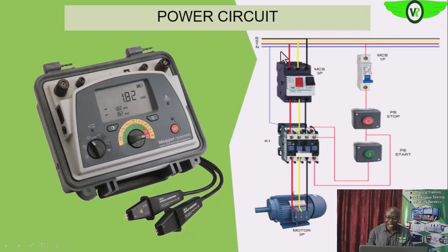So how we do it is that once you have the motor connected like this, you can test with this circuit breaker open and your contactor closed, or you can come to the contactor end, because basically these two are closed in the MCC.